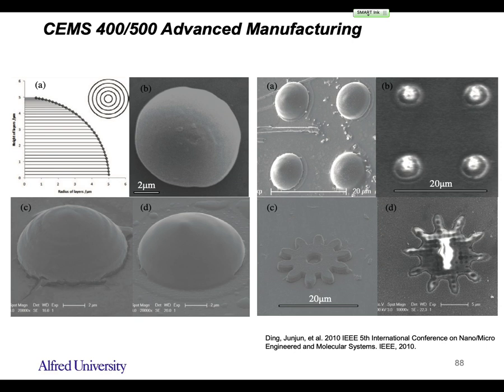So this is also made by myself. At that time I was trying to work on the micro lens array, and we tried to tune the writing pattern to increase the resolution. Because of the layer thickness, if you go to the top, you will be able to see these individual steps, because the curvature angle will be larger up to the top. So we have to decrease the layer thickness up to the top, while keeping the bottom part larger, to speed up the printing process.